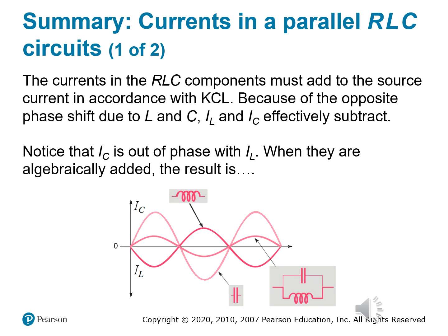In any parallel network, Kirchhoff's current law reigns supreme. The sum of the branch currents equals the total source current, but that's where things get spicy. Our capacitor and inductor are always fighting out of phase. So the inductive current, I sub L, lags the voltage by 90 degrees. The capacitive current, I sub C, leads by 90 degrees. So the net result is that they point in opposite directions on the phasor diagram.